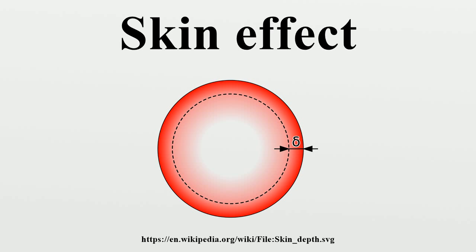Let the dimensions A, B, and C be the inner conductor radius, the shield inside radius and the shield outer radius respectively, as seen in the cross-section of Figure A below. For a given current, the total energy stored in the magnetic fields must be the same as the calculated electrical energy attributed to that current flowing through the inductance of the coax. That energy is proportional to the cable's measured inductance. The magnetic field inside a coaxial cable can be divided into 3 regions, each of which will therefore contribute to the electrical inductance seen by a length of cable.